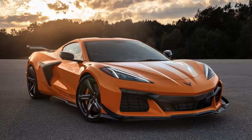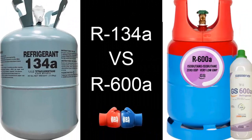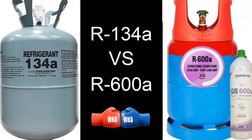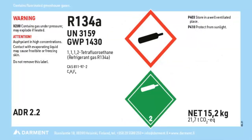The main advantage of R600a is its low environmental impact and excellent thermodynamic properties, which contribute to its increasing use. R600a does not harm the ozone layer and has a global warming potential, GWP, of 3. On the other hand, R134a also does not harm the ozone layer, but has a GWP of 1430, which, over the years, is starting to face challenges with stricter environmental regulations.